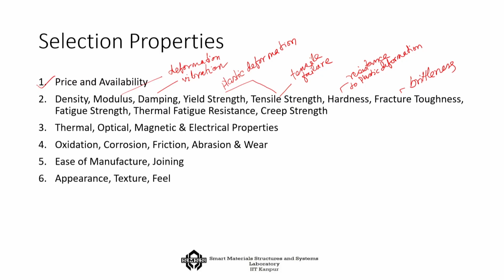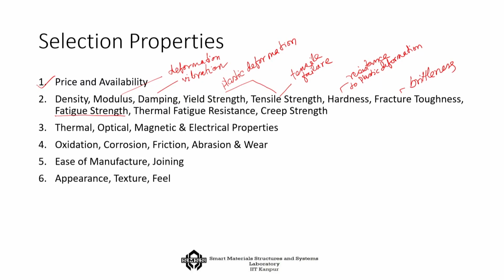After a few cycles, you just press a little bit of load, you will see there is no ductile failure, it is just like a brittle material, it will snap out. So, that we always try to avoid. So, wherever there is a dynamic loading, the fatigue becomes very important. So, this is against the dynamic loading.